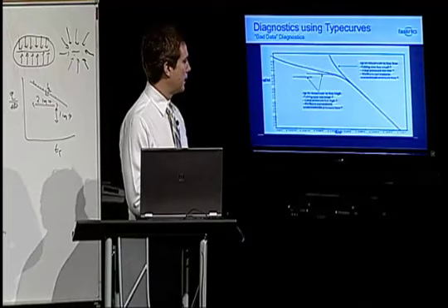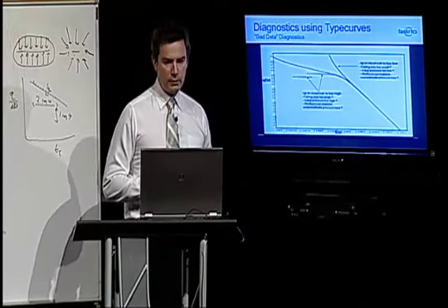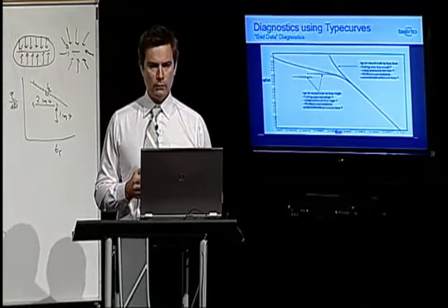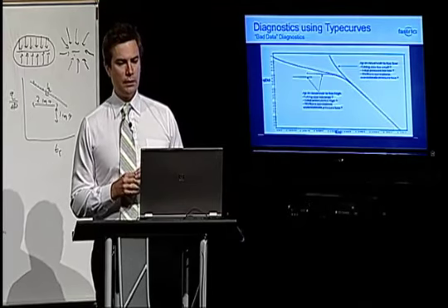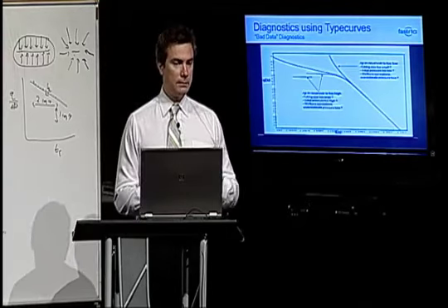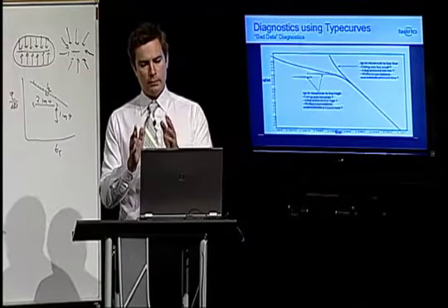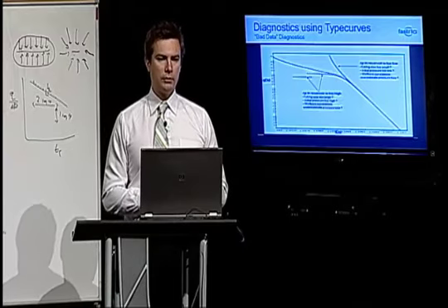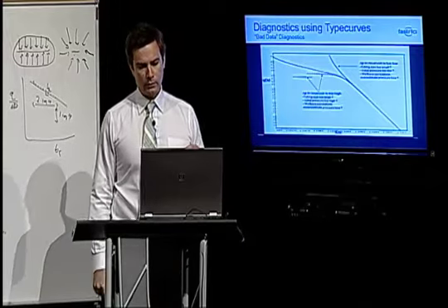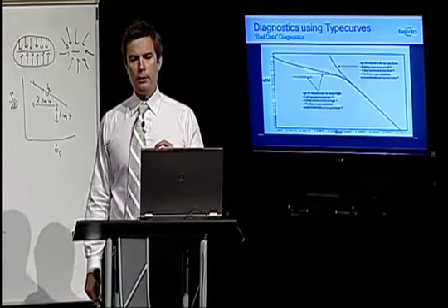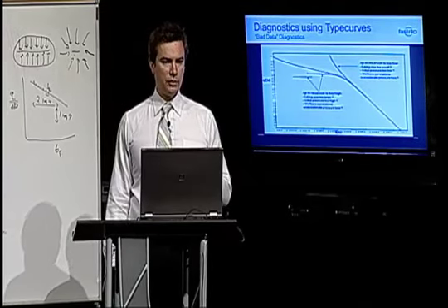Okay, one final diagnostic that is important is the bad data diagnostics. And as we showed before, right at the beginning of this discussion, bad data may be more prevalent than you think. It may be bad simply because it's measured in the wrong location. If I measure the pressure downstream of a choke, when there's a big choke in place, I'm not going to get good quality pressure data. But there's other places where we can go wrong here. Usually, if it's an onshore well, the production rates are going to be good quality because that's what the company is getting paid on. It's the flowing pressures that could be questionable.